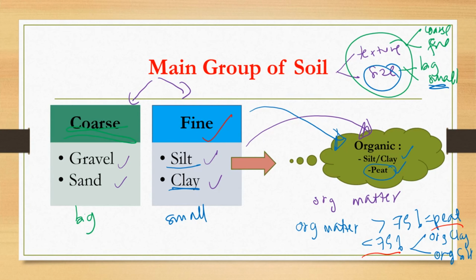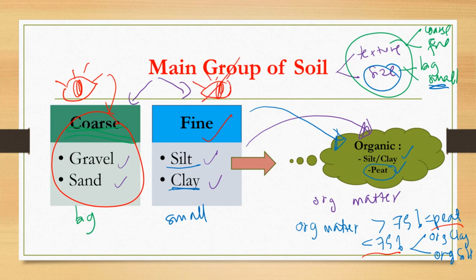If you're talking about coarse, it's simple. In these kinds of soil, the grains are well defined and may be seen by your naked eyes. The individual particles may vary from perfectly round to highly angular, reflecting their geological origins. However, fine grain soil, which is silt and clay, has particles smaller than 60 micrometers. It means that you cannot see them with your naked eyes. You can still see coarse grains, but for fine, you cannot see. It's at a microscopic level.